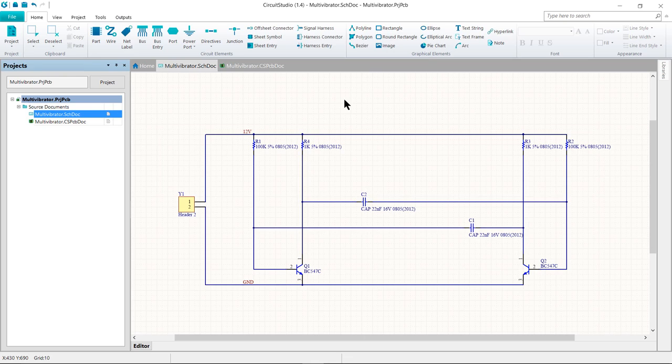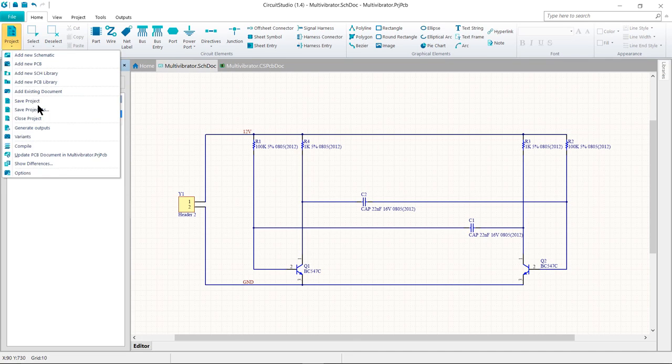So when the design is compiled, a list of pins in each net is built in memory. The type of each pin is detected, for example, input, output, passive, etc. And then each net is checked to see if there are pin types that should not be connected to each other. For example, an output pin connected to another output pin. The Connection Matrix tab of the Options for Project dialog is where you configure what pin types are allowed to connect to each other.